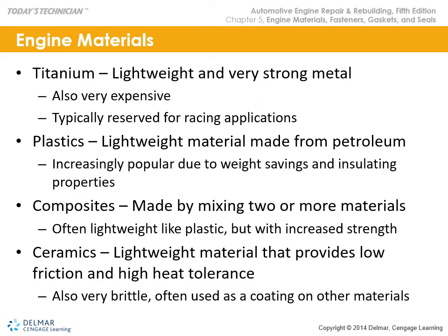We have titanium, which is utilized in part in surfaces. We don't see large titanium parts in automotive or truck, but we see a lot of plastics and composites. Composite materials like the oil pans in engines have become composite. They're lightweight. And we see ceramics, coatings, and materials that are utilized in high heat applications. So ceramics can hold their geometry in high heat.